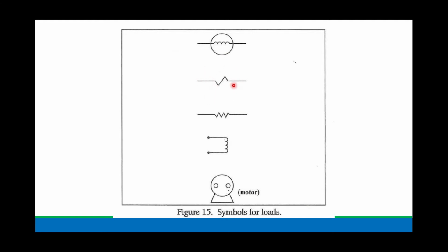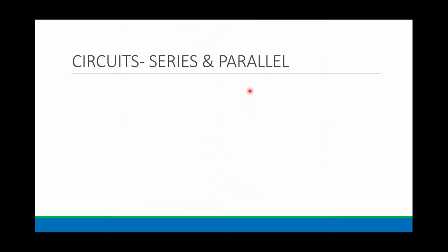This is the coil, the symbol you really want to focus on, because if I can find that on my wiring diagram, and it'll be addressed with a letter and a number, it could be C1 or K1 or whatever, it will have switches addressed to it. And that will tell you what it's going to turn on and off on both the line voltage and low voltage side. So now we know our parts and pieces: power, switch, and load.